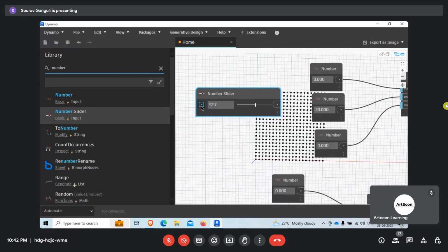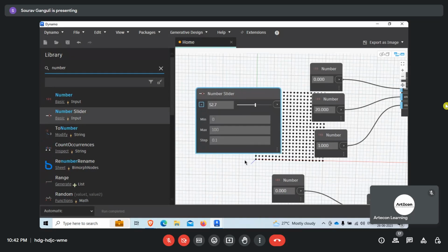So we click on this small arrow over here, and this drop down comes up. This allows us to specify a minimum, a maximum, and a step. Step is the interval at which the slider will move. Now you can see, since it's moving only at an interval of 1, decimals are avoided. And say I will have a minimum size of 5 and a maximum size of, say, 40, just so that it does not break my system.